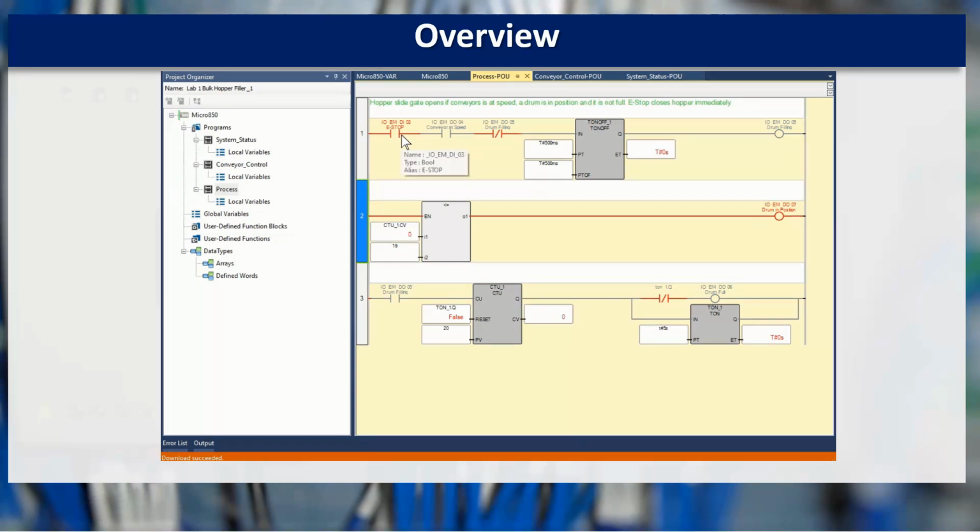When the e-stop was not tripped, you waited to see the conveyor at speed. So this global variable, digital output 4, had to be energized from the program that you were going to create. Once that was true, it would initiate a turn-off timer to flash off and on for half a second. Every time it did that, it would turn on digital output 5. Now when you look down at the bottom, digital output 5 in turn would start a count.